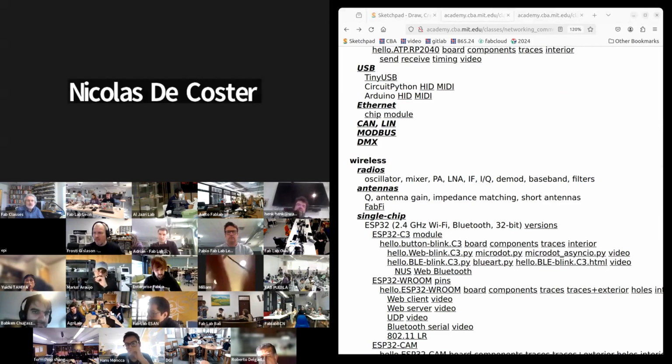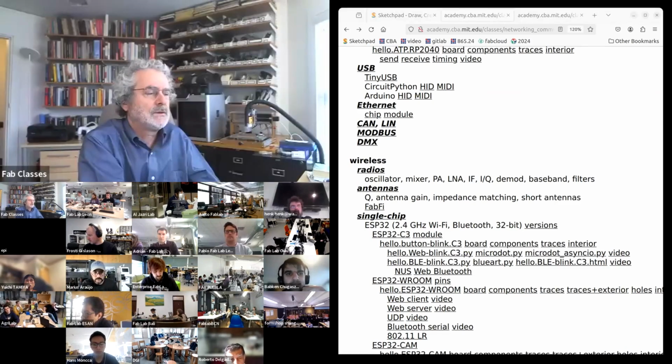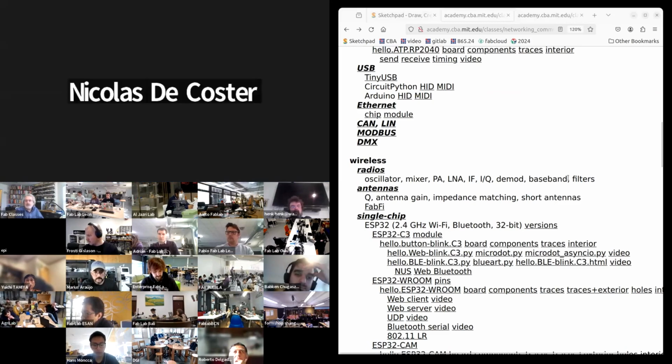Okay. On the Tinies, there is some LIN-related peripheral that lets you synchronize the UART data rate. So even with the simple RC oscillator and so on, you get good enough synchronization. You can do LIN actually on the chip, but you are not obliged to use the LIN protocol. You can just use the LIN synchronization.